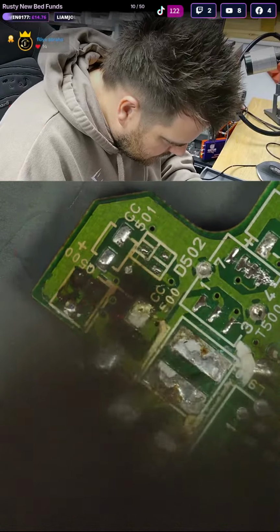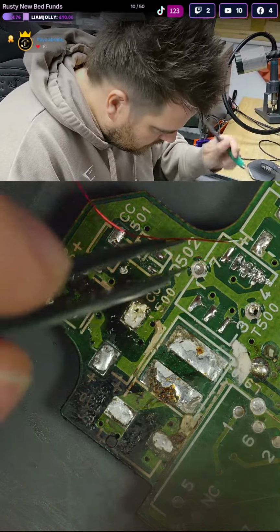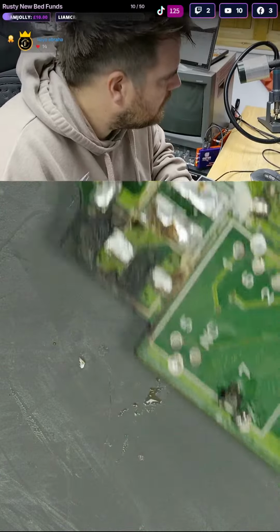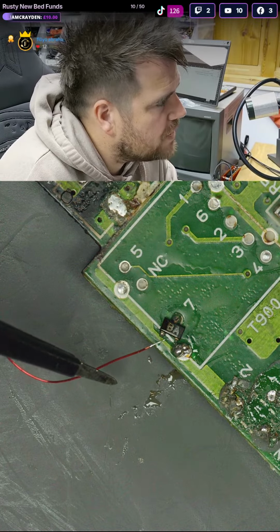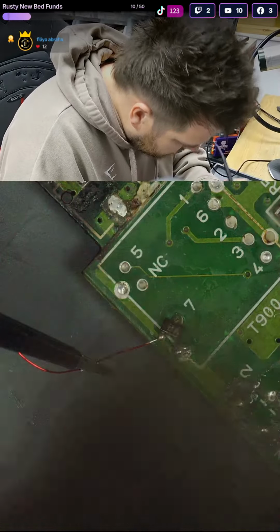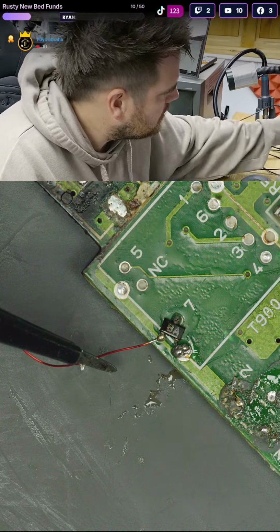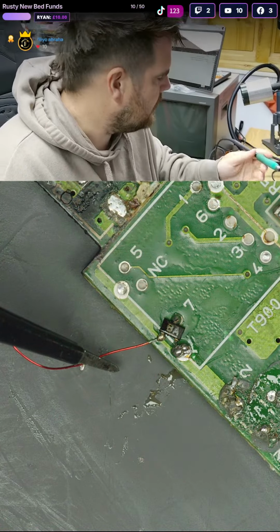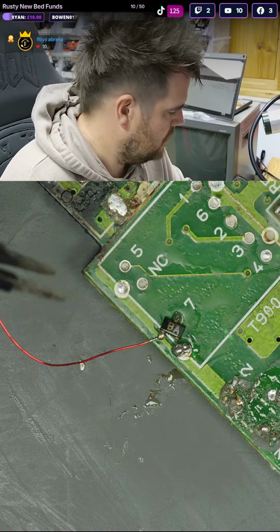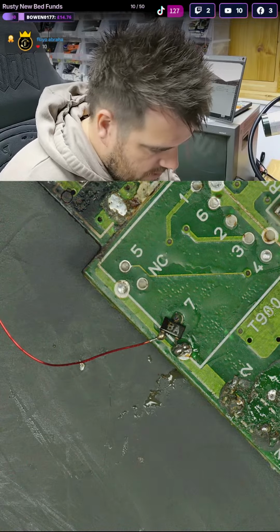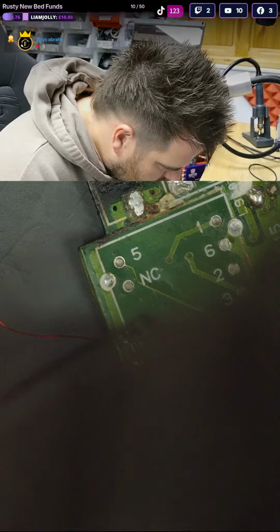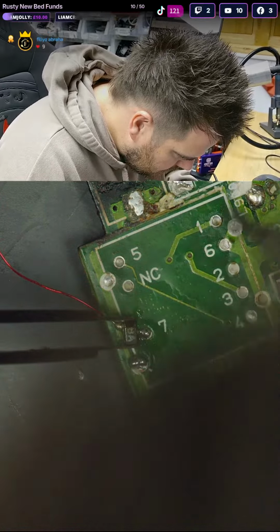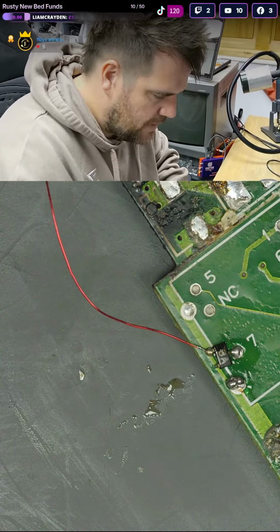So we're going to get pin 1 on this pin here. We are transplanting chips over from an original PC Engine GT. Well, my soldering iron tip is failing again. I think I need to buy some new arms for these irons. Right, so pin 1's on. We can then turn this around, move it slightly, put pin 2 on, which is red.